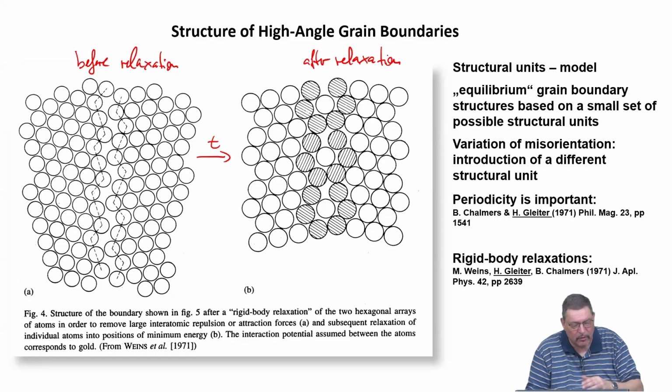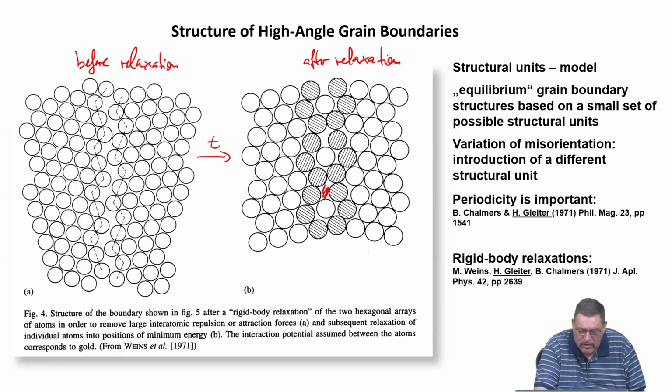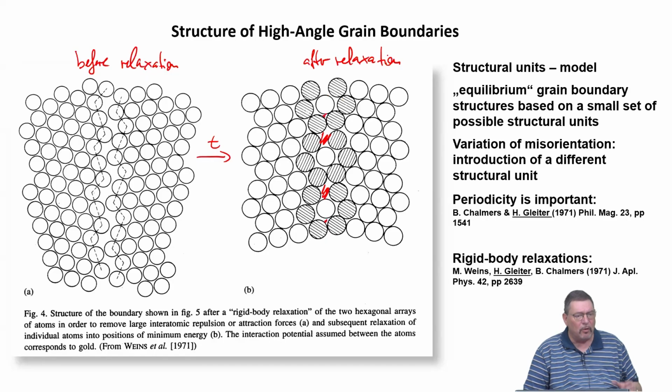Then this shuffling occurs, and so it means that there is now a much more ordered structure in the high angle grain boundary plane, and also much less excess volume. And also the distribution of excess volume along the grain boundary plane is more uniform. It's not completely uniform because you still have concentrations here and maybe less here or here. But overall, it's reduced.